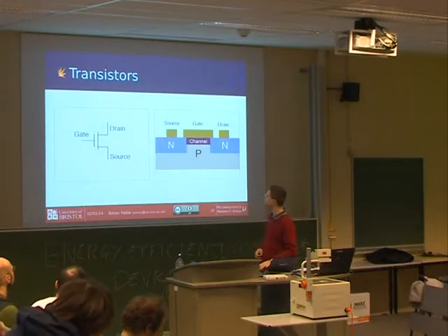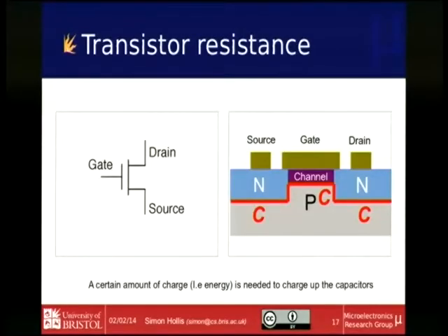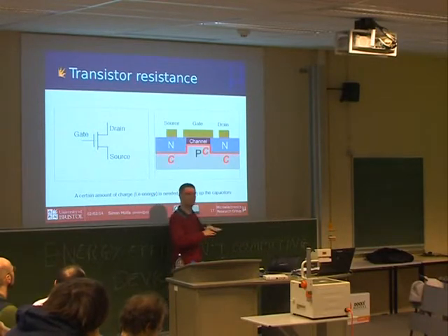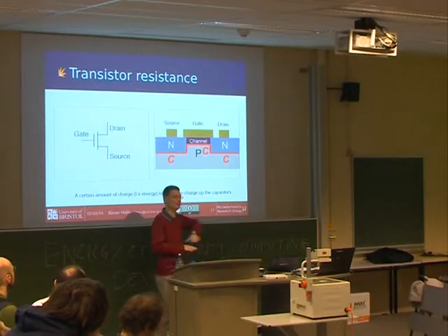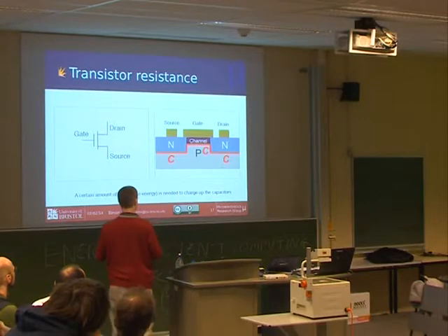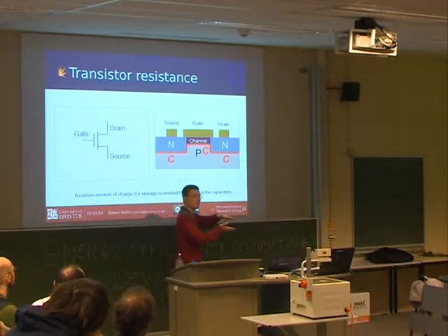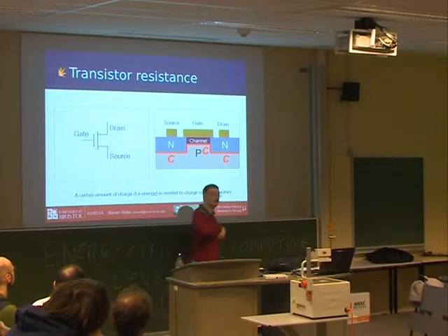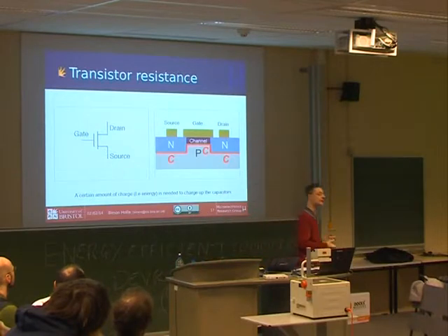Why? Well, the first thing is, you can think of, from one point of view, the two materials as being separated together. I've just built a capacitor. This is a lovely parallel structure. That's how our industry has done so well, making these big, mass-produced, very flat devices. So I've got a big parallel structure, so what I've built myself is a parallel plate capacitor. And it's about as long as a transistor. So if I change the voltages in any point in the circuit, I actually start charging and discharging the capacitance at that point in the circuit. So that means that I have to do some work.